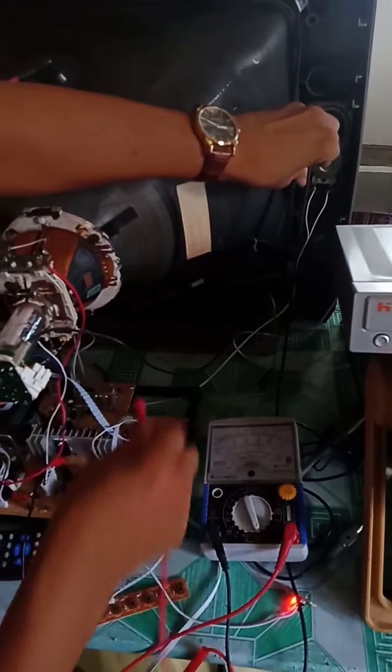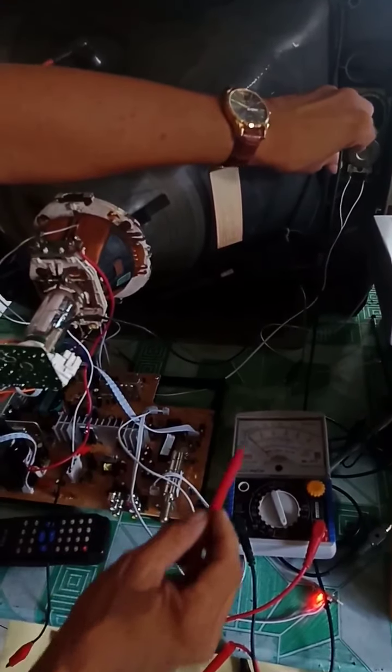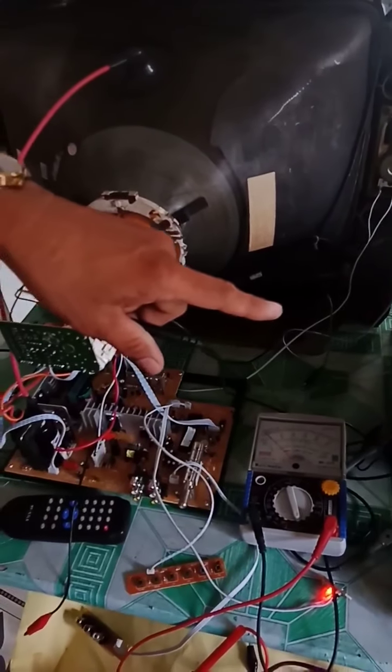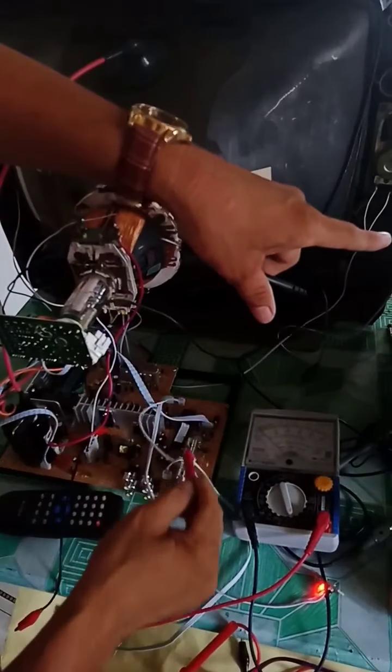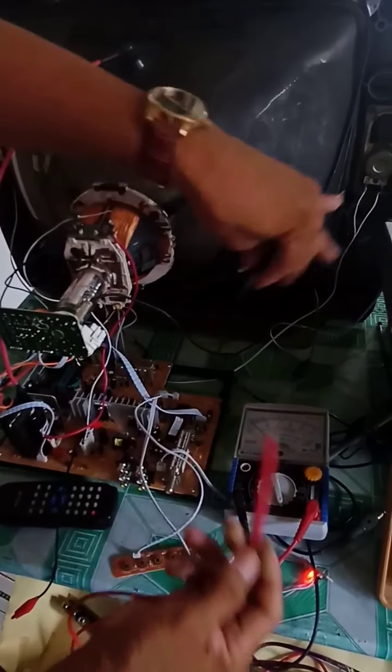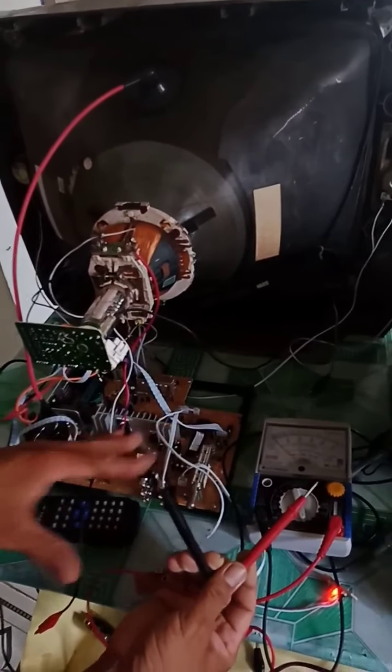So it goes like that. But if it is here, there is no deflection. Do not connect your negative side to this metal because it is connected to the power line. They are not connected to these metals here, which is at the cold circuit. Remember that there is a hot circuit and the cold circuit.